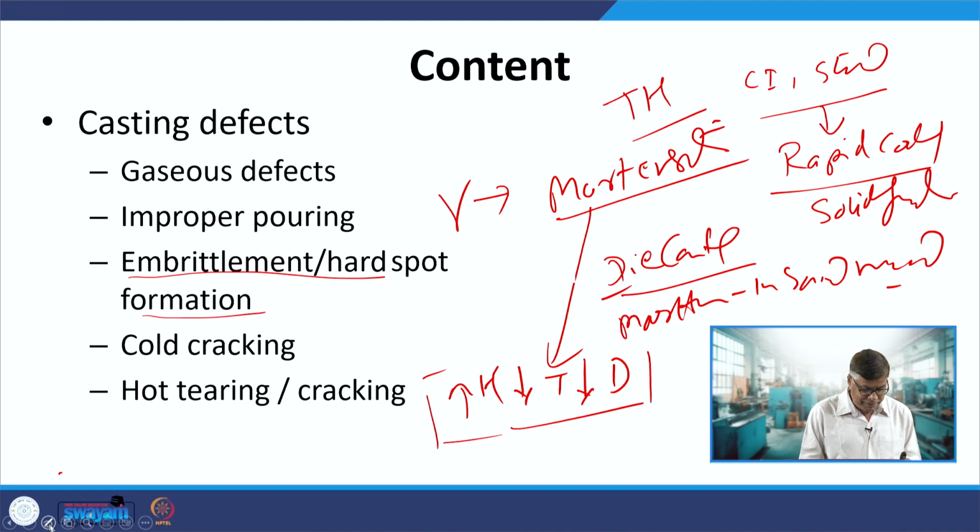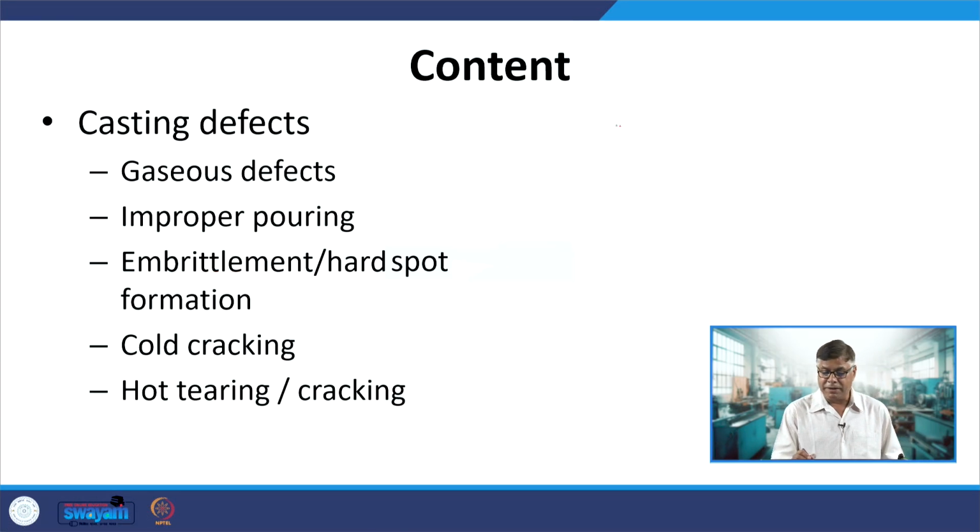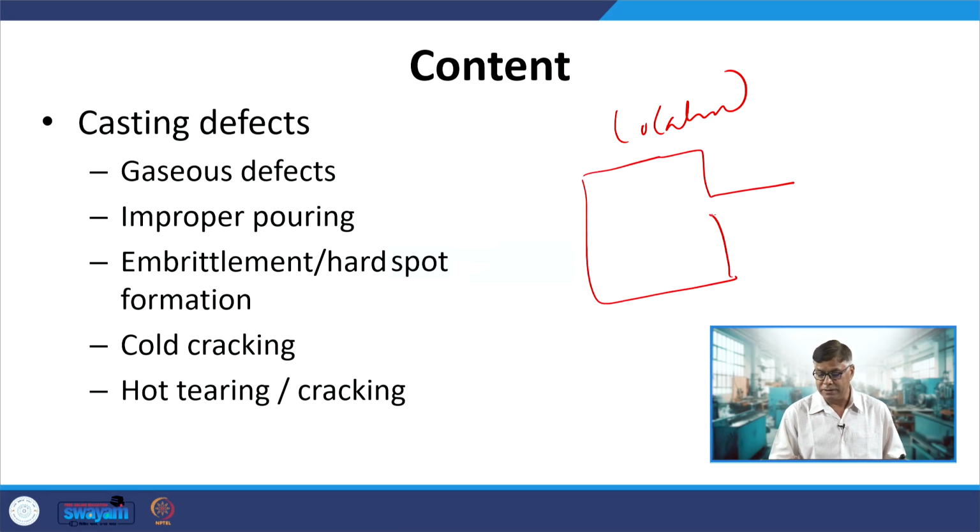Whenever this kind of transformation occurs in a localized manner, say one section is very thick and another section is very thin, the thick sections will experience a low cooling rate, or slow cooling. On the other hand, the thin section will experience a high cooling rate.